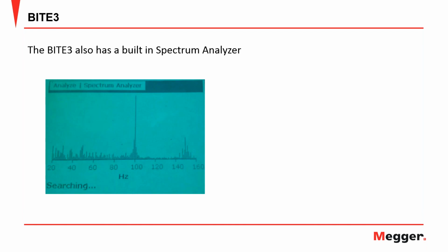If I see it sitting at 50 hertz, I know there's a problem at the charger. The charger has an open diode in it or an open rectifier. So that will show me that problem right off. And I have found that quite often on problem strings.